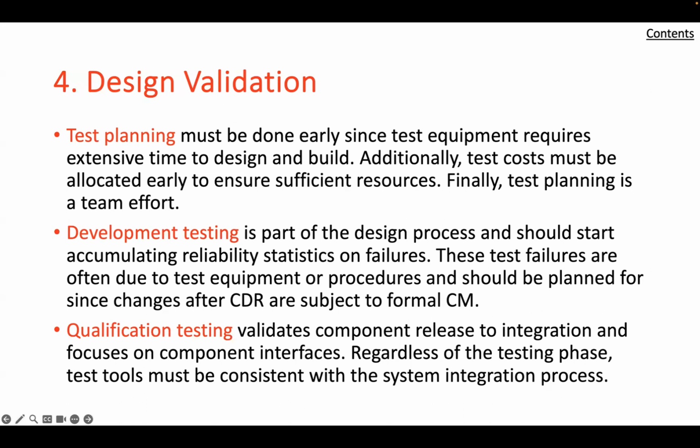It should be anticipated that design discrepancies will be found and design changes will be needed in order to comply with requirements. Thus, component testing is very much part of the development process. Changes at this point must be introduced via an engineering change notice agreed by all cognizant parties to avoid chaotic, non-coordinated change.